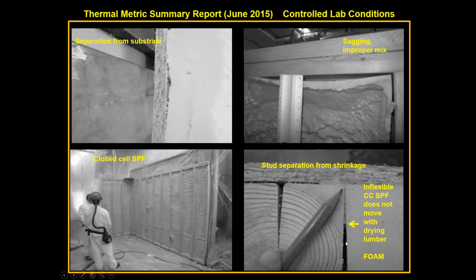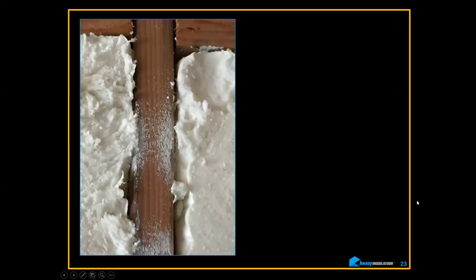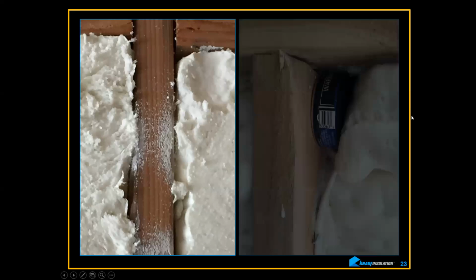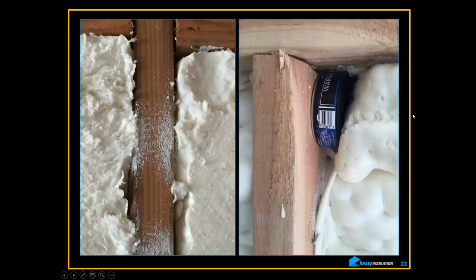This is the foam from here to here. This is all foam. And then, of course, this is lumber. And you can see what happens when they shrink and twist. You open these gaps up, and you're in a big world of hurt as far as thermal energy goes. Same thing here. You can't tell if the cavities are filled. And when you want to fix it because you're not going to come back, well, just put your favorite can of spray foam in there and that'll cover it.